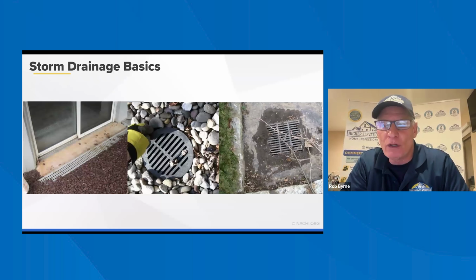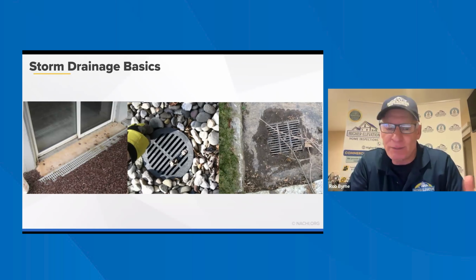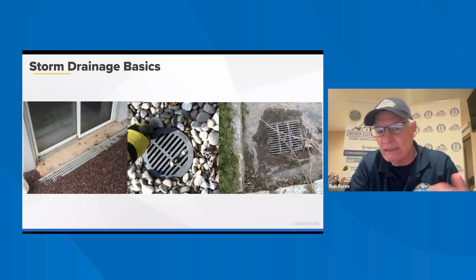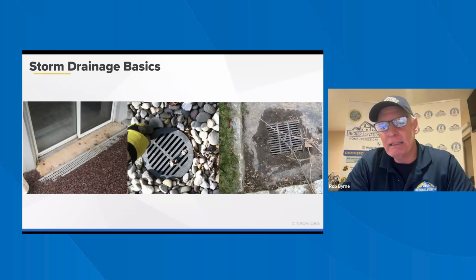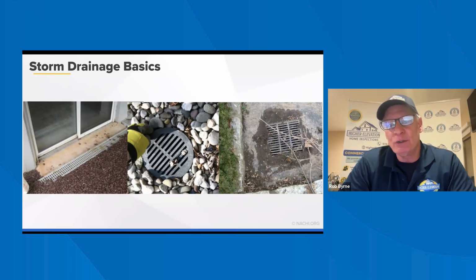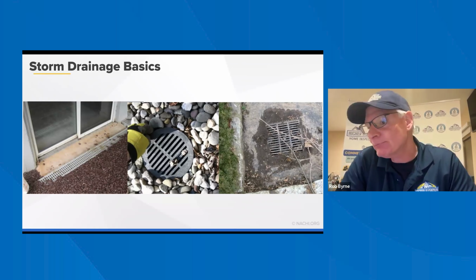The water runoff cannot go into a sewer line. It can go into a storm drain, which gets dispersed differently. It can go into the bays and stuff like that because it's a storm drain. But yeah, we mention that if we see it. We talk to the client about it, because you really don't want to overload the sewage system with rainwater.